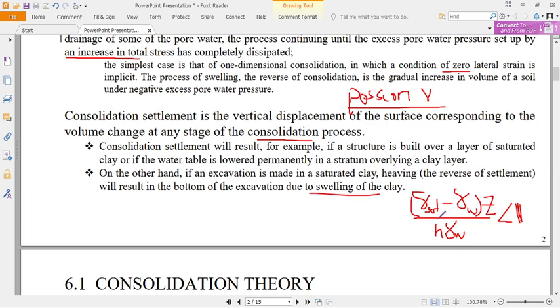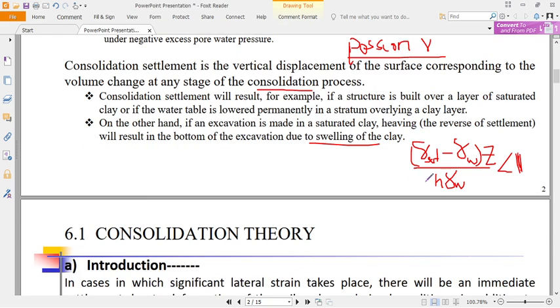The soil with the water, with this pressure of water, since the resistance offered by the soil skeleton, the effective stress, is less than the applied stress, which is the pushing force, or the tensile or tearing stress coming down, it will push the soil apart, creating what you call a heave. Is that okay? The soil will separate, and so we have what you call piping or heaving.